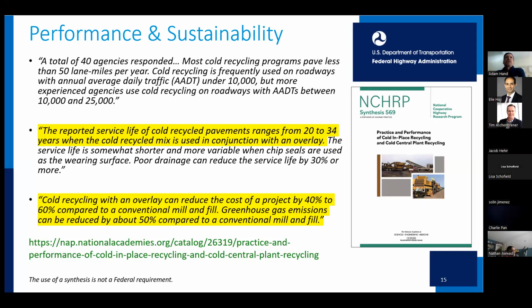Two key observations from that document were that service lives for cold recycled pavements range from 20 to 34 years when used in conjunction with an overlay, so they've got a surface, right? And then cold recycling with an overlay can reduce costs of a project from 40 to 60%, and greenhouse gas emissions can be reduced about 50%. That was very encouraging information.